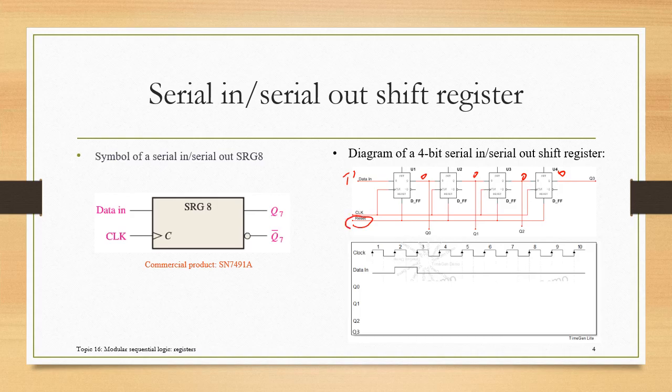Because we have a synchronous reset input here, everything is reset. So at the second rising edge, because D is 0 right before this edge, Q0 will follow D, so it stays 0 until the next rising edge. Then at rising edge 3, we get 1 here, so Q will also change to 1 and keep that value until the next rising edge. And here, D is 0, so it turns back to 0 and stays 0.